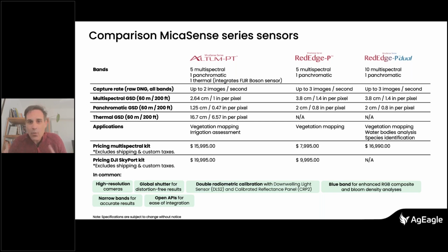So how would I recommend you to use all the data of the camera, to take advantage of the high resolution of the pan camera and the spectral information of the multispectral camera? Because they are co-referential, of course. So you can use the, not the pan sharpening, the panchromatic band for segmenting your image, for example, or to find the borders of the objects, and then colorize that information with the multispectral data.